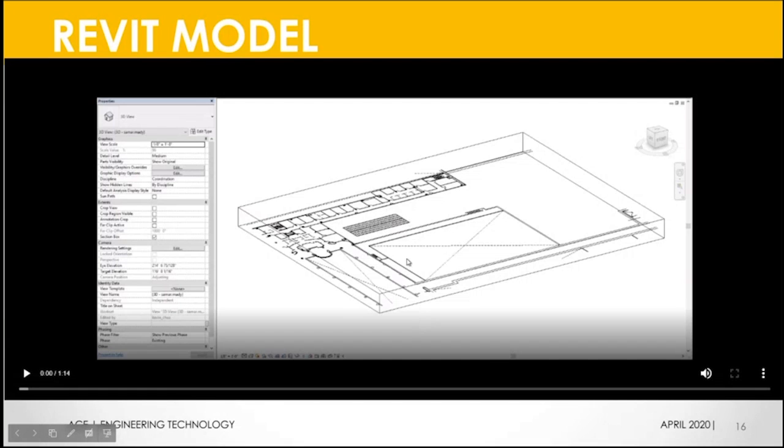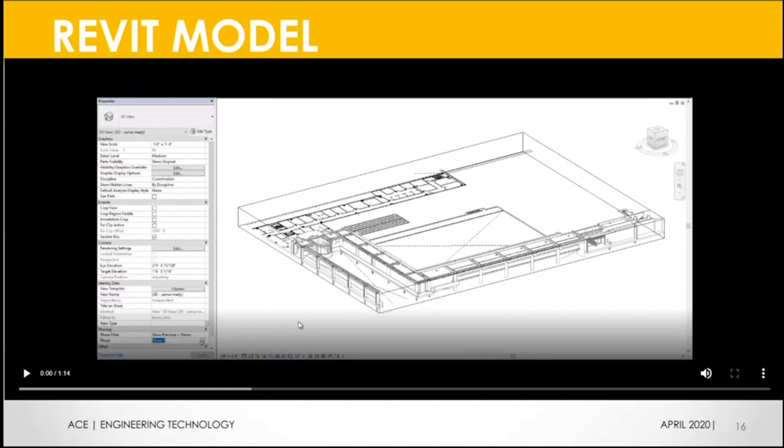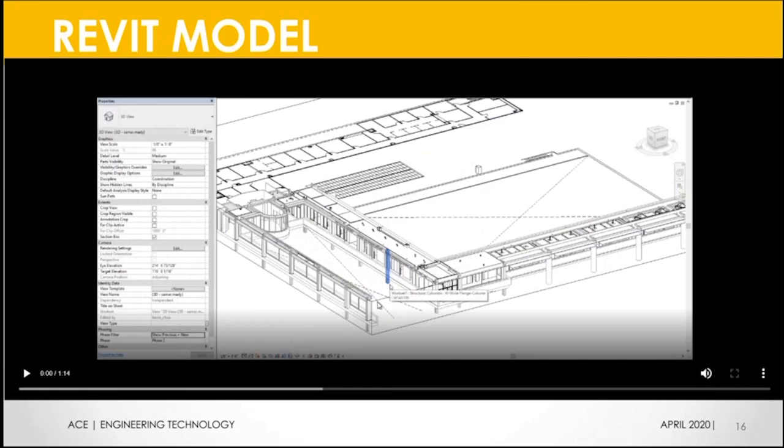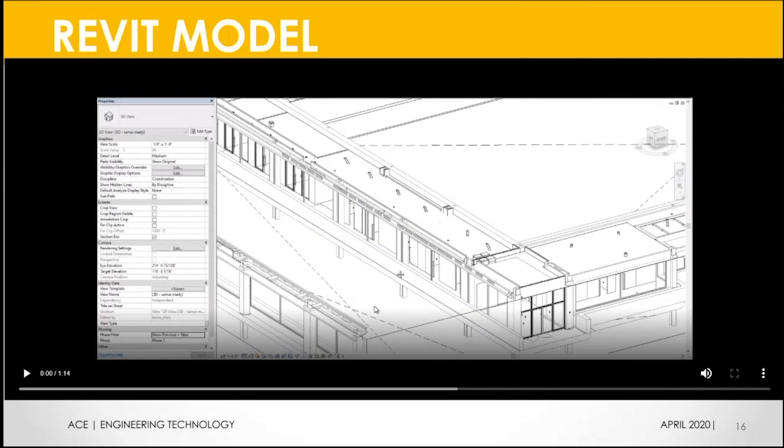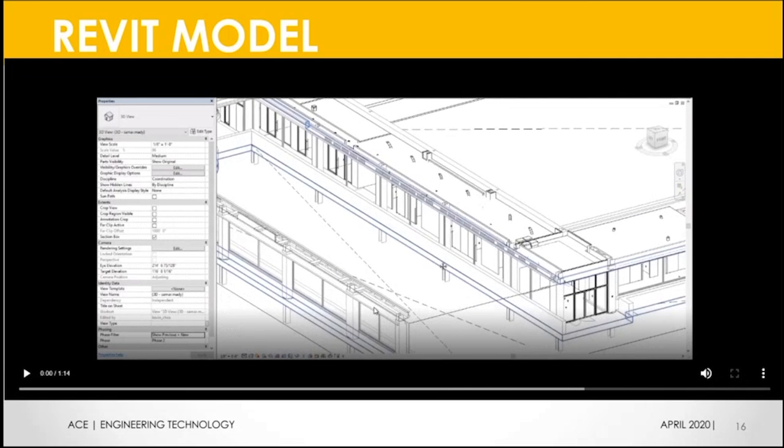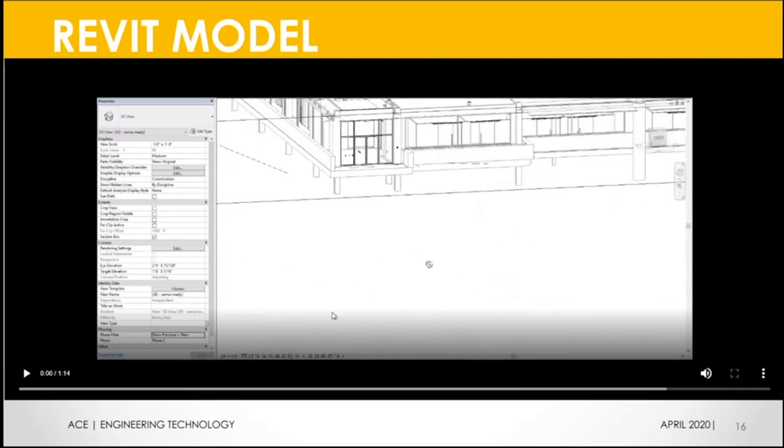In this project, we decided to utilize Revit because the intent was to provide construction documents, not just conceptual drawings. So what we ended up doing, utilizing the scan, and here you see at the bottom, you're playing with the existing conditions. You can turn on different filters, so you can see this is the existing building, and we start adding the phases of the work so we can phase what we are trying to present to the client. It gives them a better understanding of what they have and what they expect of the final product, and lets us build the project in the virtual world before it goes to construction.